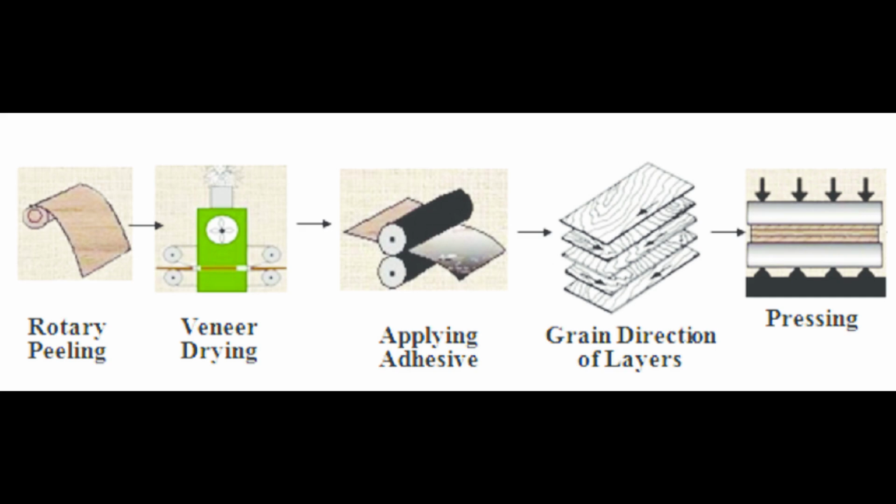An adjustable nose bar, which may be solid or a roller, is pressed against the log during rotation to create a gap for veneer to pass through between the knife and the nose bar. The nose bar partially compresses the wood as it is peeled. It controls vibration of the peeling knife and assists in keeping the veneer being peeled to an accurate thickness. In this way, the log is peeled into sheets of veneer, which are then cut to the desired oversized dimensions to allow it to shrink depending on wood species when dried.